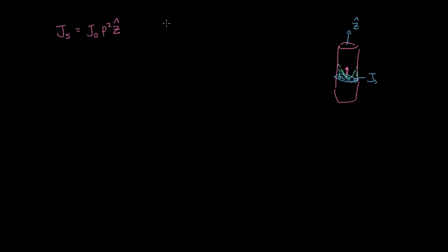As I mentioned before, we're trying to do the conversion between the current density and the current. So the question in this example is, what is the associated current? Current density is a density, right? Amps per meter squared. So to convert that into current, you just integrate that over the entire area. So I have the amount of water flow density going through this cross-sectional surface as a function of location. If I wanted to know the total amount of water flowing through it, again using the water analogy, then I just add it all up across the entire surface.